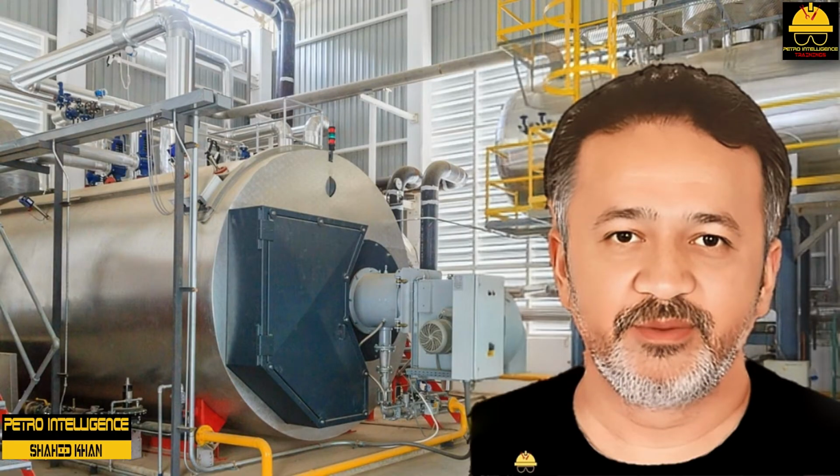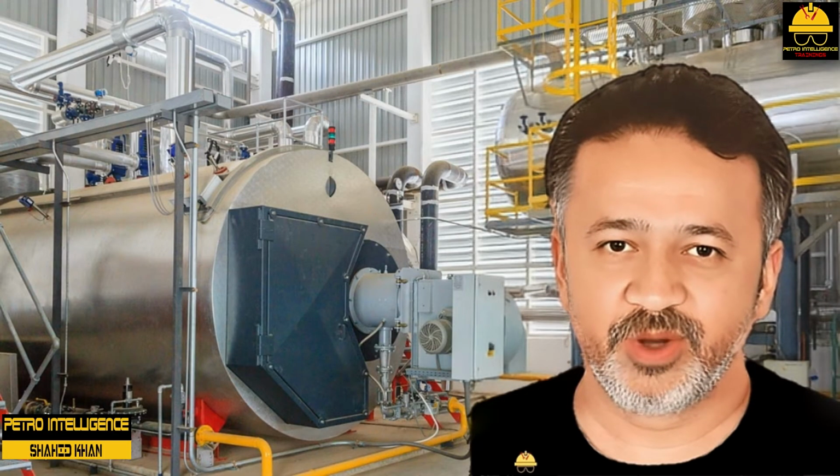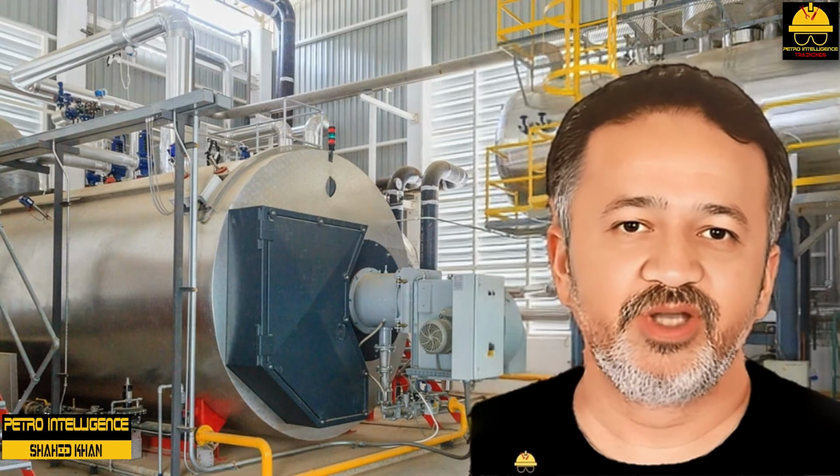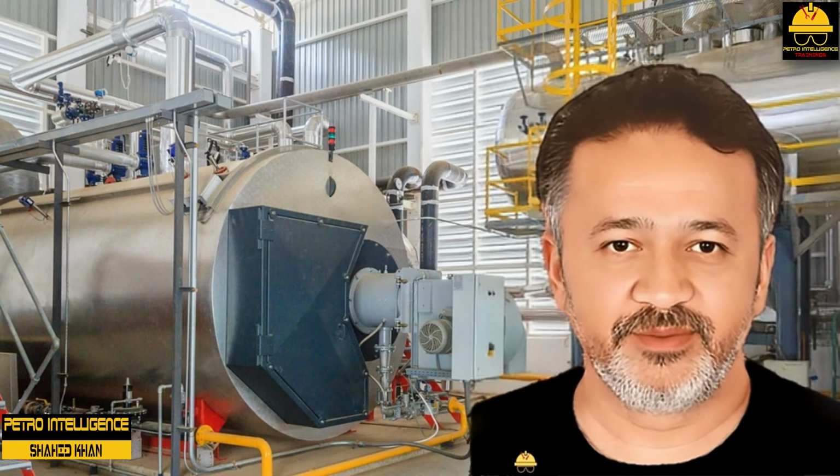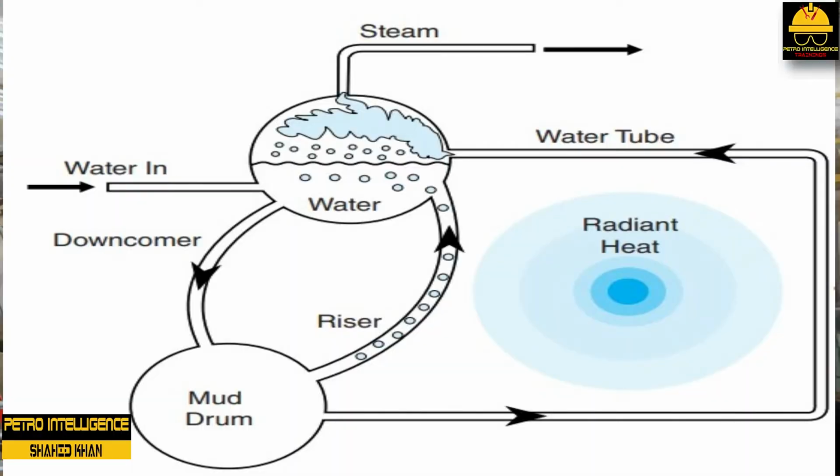We will now discuss boiler functions. When a boiler is being started up, the following process occurs. The furnace, which contains cool water in drums and tubes, starts to heat up. When the burners are lit, hot combustion gases begin to flow over the generating tubes, riser tubes, downcomer tubes, and drums. Radiant, convective, and conductive heat transfer begin to take place. Hot gases flow out of the firebox into the economizer section and out the stack.